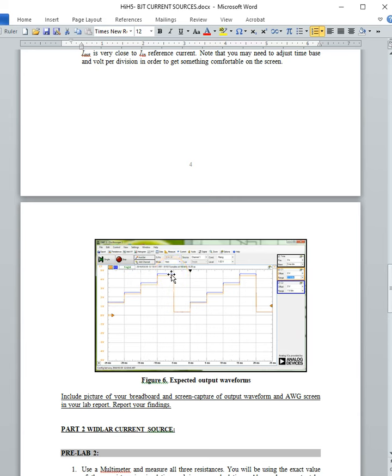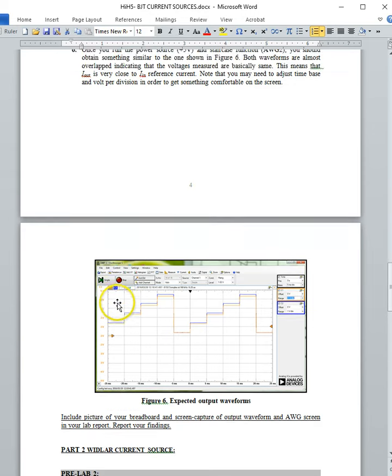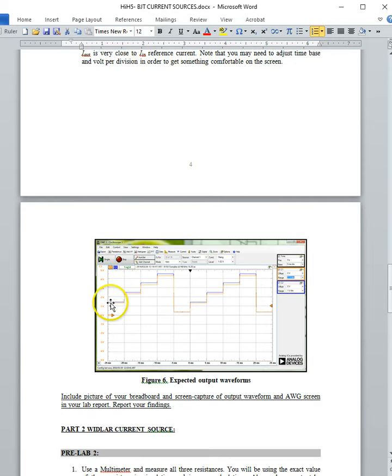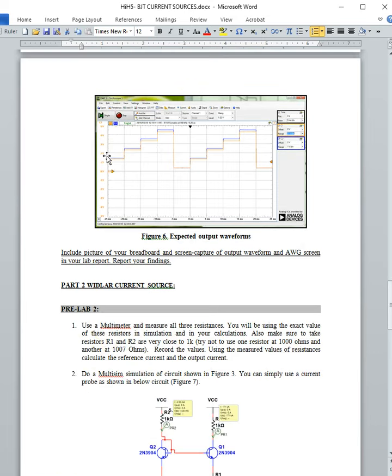So what we're measuring are the resistor voltages. You can view this as the currents; if you just think of this as a milliamp, you get like 1.5 milliamps here, maybe 2.4 milliamps. In other words, this indicates that output current and reference current are roughly equal to each other. Of course, the transistor matching is important, so we're probably not going to have a perfect match here. Also keep in mind that output current tends to be a little less than input current.